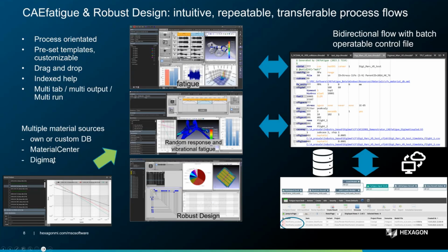And we have a very advanced workflow with Digimat, which means that some tough materials cannot preemptively be described. For example, with short fiber reinforced plastics, the material really depends on the location because it's an injection molded part. Depending on where you look at the material, it has a different fiber density. And depending on how you load it, it has a different loading direction or a different R ratio. So all these things mean that the curve has to be detected on the fly. We can do that with Digimat. We're also working more on composites with Digimat for this capability. So that's the material angle.